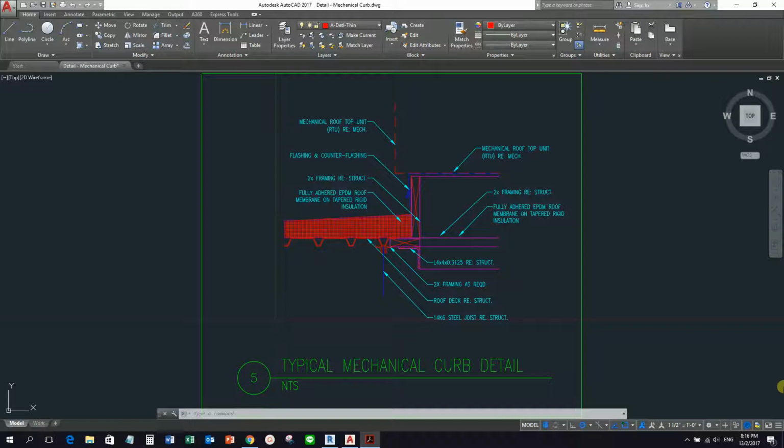So instead of redoing the whole process in Revit using those annotations, those detailing tools, why not just import your AutoCAD drawing in Revit and then you just do some simple editing there. Okay? So it saves time and effort and avoids duplication of work.